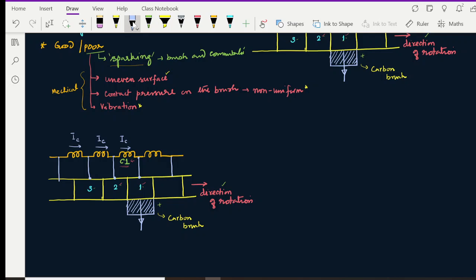And we know that through our winding diagram, we will be placing the brush where the current direction of the two coils are towards the commutator segment or away from the commutator segment. So with that, the current direction in this particular coil is going to be like this. So what we have done, we have just marked the current directions in all the seen coils in a given instant of time.